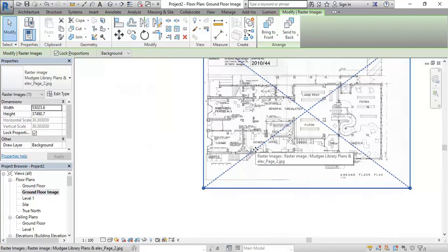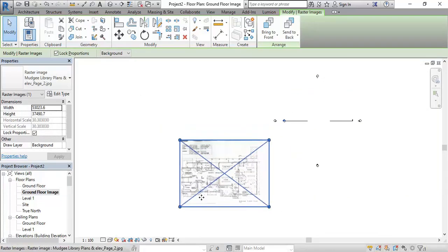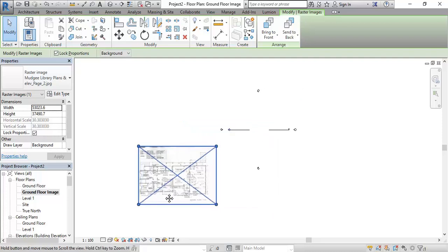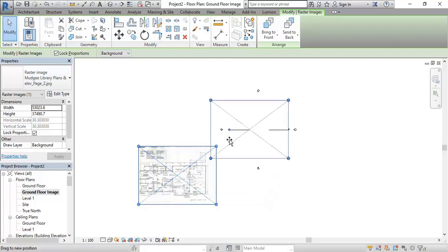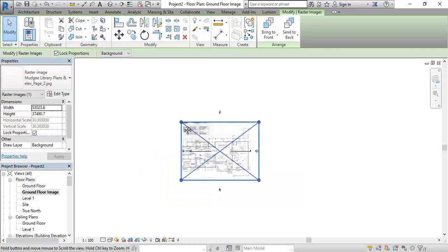Oh no, you must have clicked twice. So just click the base point, then click the second point, then type. So select the image again. Then press the scale button. You write 1000, right? Yep, that's it, and then enter. And you should see it get smaller. So you just need to be conscious how many times you're clicking. Yep, that's it.